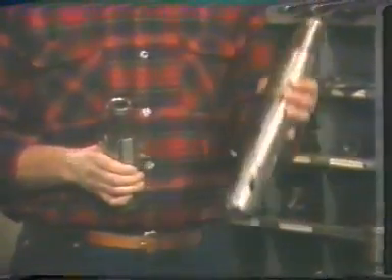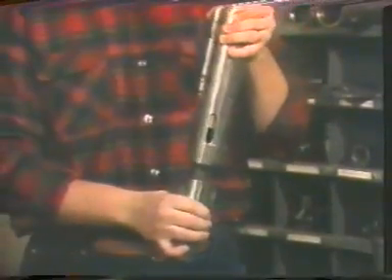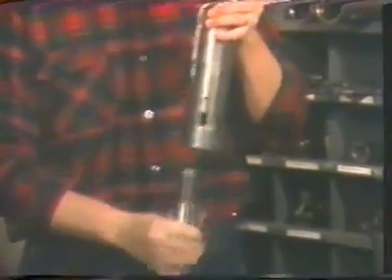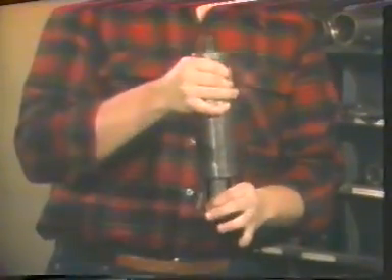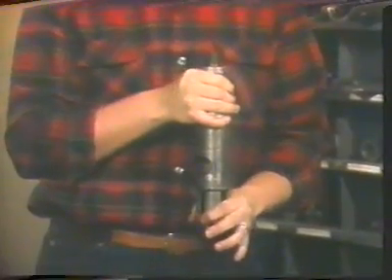Some devices are constructed with fishing necks that require the pulling tool to go over the outside of the neck. Other devices are constructed with fishing necks that require the pulling tool to latch inside the fishing neck to retrieve the device. Whenever a subsurface device is latched in the tubing bore, there is always the possibility that it may become